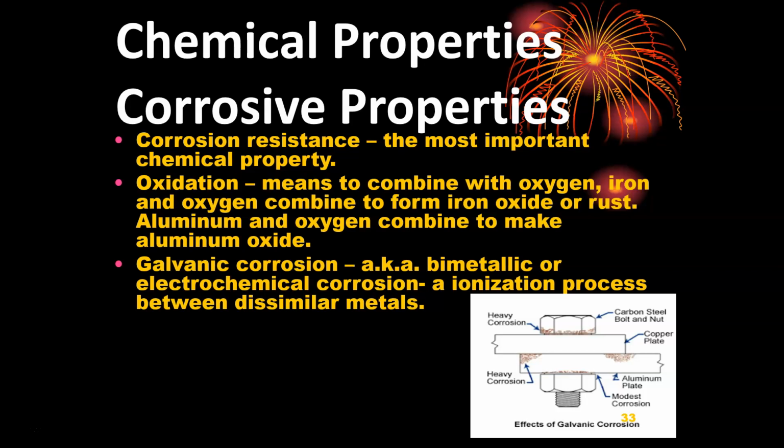Common types of corrosion. Some you've seen quite often. Oxidation, the reaction of a material exposed to air. Example, iron and iron-rich steels oxidize to form rust. Galvanic corrosion, also called bimetallic corrosion, is an electrochemical process in which one metal corrodes preferentially when it is in electrical contact with another in the presence of an electrolyte. Electrochemical corrosion, corrosion that occurs when electrical currents set up on materials in a liquid or moist environment. You've seen this. The most common is battery corrosion.